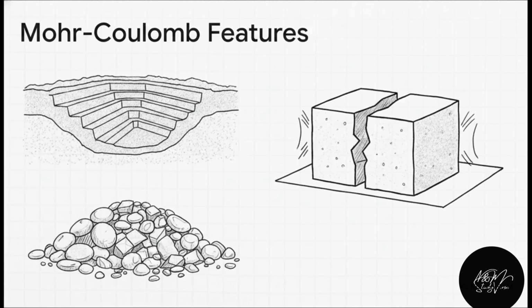While it does have a few limitations when you get into really highly complex rock masses, this elasto-brittle plastic model is incredibly well suited for evaluating the stability of mining and geotechnical problems. And by elasto-brittle plastic, I mean it accounts for how materials stretch, snap, or permanently deform. It effectively models soils and gravels, evaluates both peak and residual strength, and even accounts for volume dilation, which is just a fancy way of saying it predicts how soil expands when it breaks.